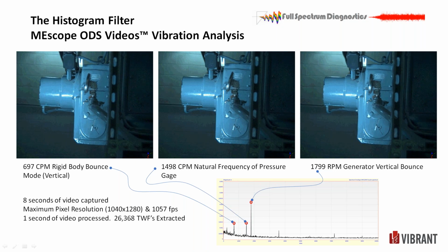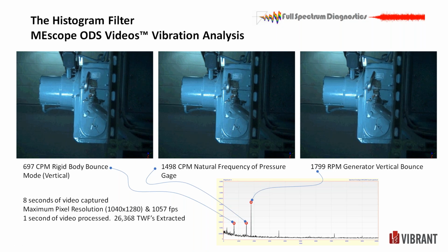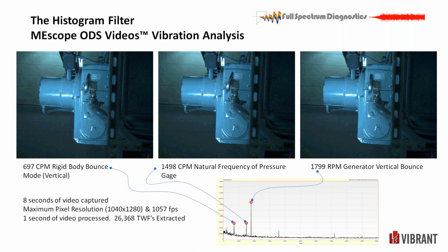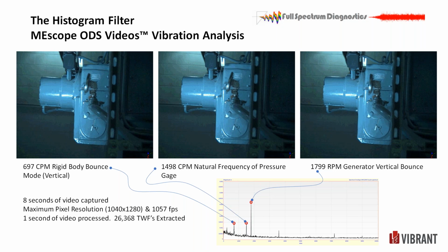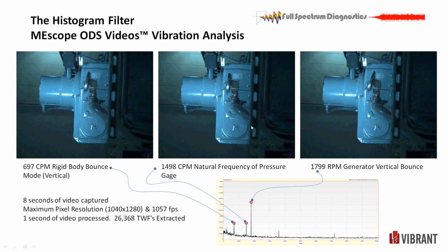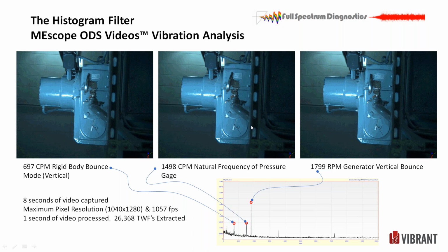Remember I told you there's a boundary on the floor between the slab and the building structure. That slab that all this is mounted on, it's a generator, a gearbox, and a turbine, all in a big steel frame, and it's mounted on a slab that I believe is 1.5 feet thick, and it's mounted on pillars from the basement. So that whole slab structure is bouncing.